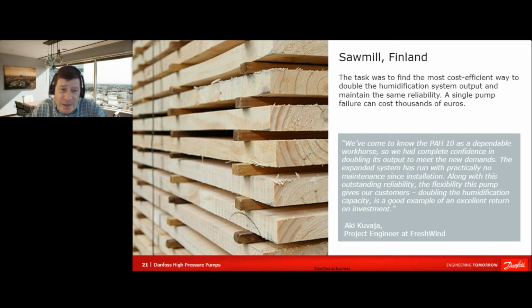For example, I can come back a little bit to my previous words about this high pressure water mist. Here in this picture you can see these gaps between the lumber in this bunch of lumber. Think, if you have a low pressure system and heavy droplets which go down pretty fast because of gravity, how can the moisture get into these gaps if the water is so-called raining down?